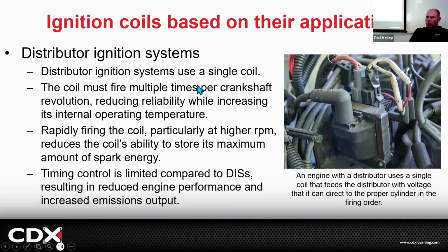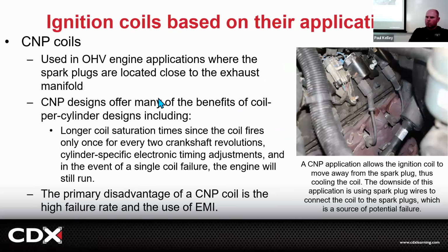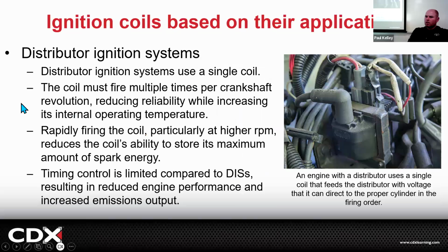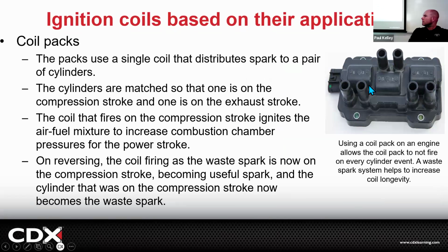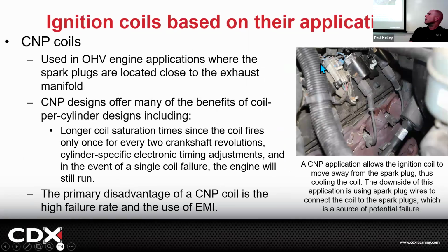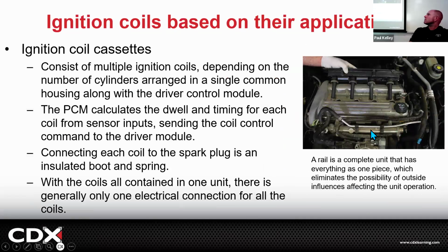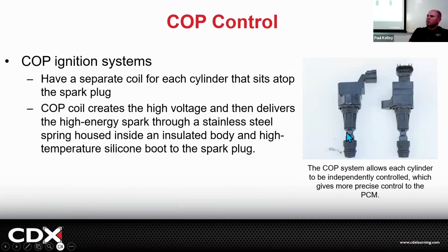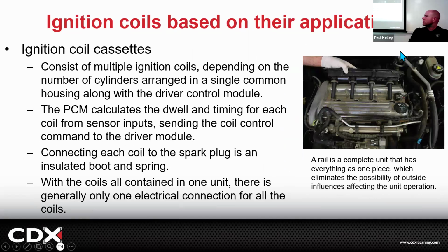All right, cool. So again, when we look at the progression, right? A lot of maintenance, less maintenance, and this is probably even less maintenance, except we have a spark plug wire. So the better system gets to be like this. Right here, this is the coil. There is no spark plug wire. Spark plug wires need to be replaced. Coils directly don't, right?